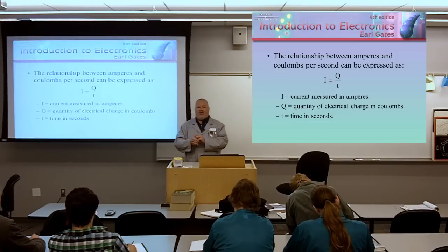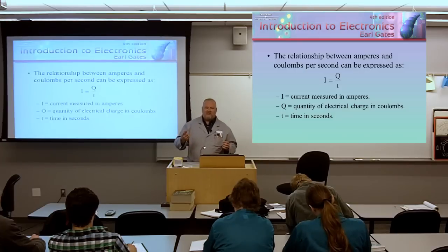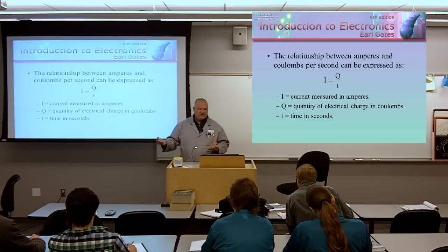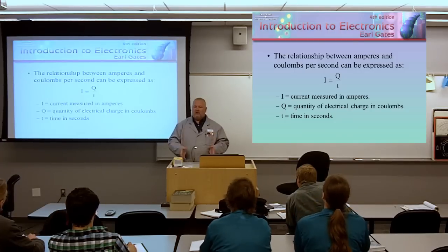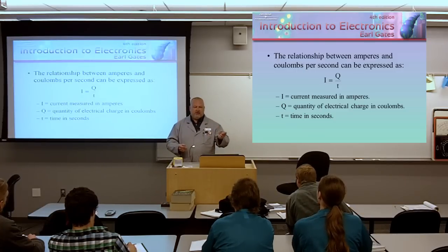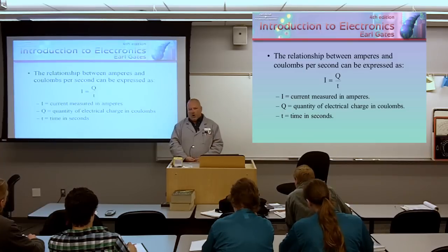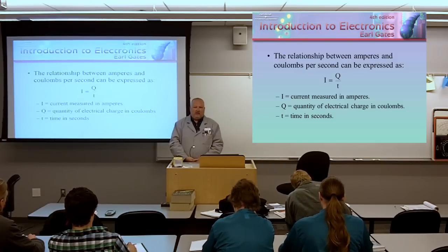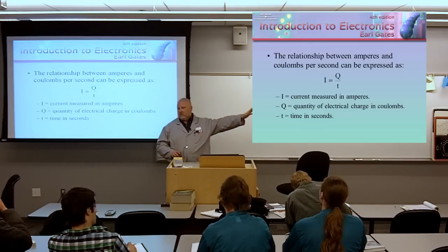So typically for household current in your home, we talked about this last week. What was that number? What's your typical utility connection from the power company to your home? That's the voltage. What's a typical box? 200 to 250. Typically about 200 amps is a typical residential connection. You know, you buy a home, you're going to see that it's typically 200 amp connection from the power pole, or if you have underground service, to your box, that big gray box that's in your house, 200 amps.